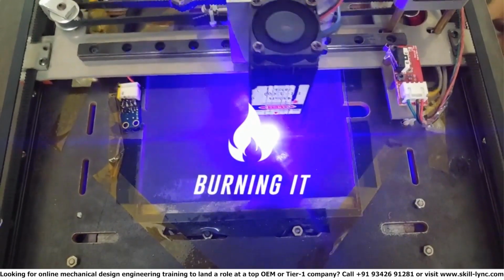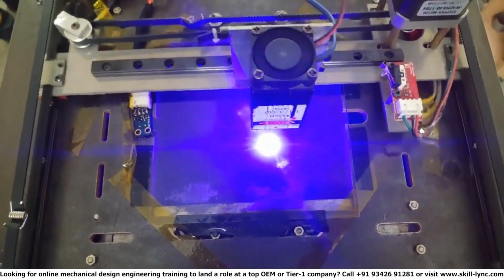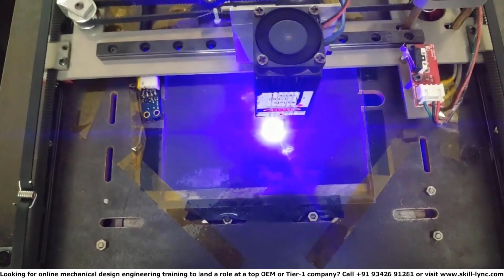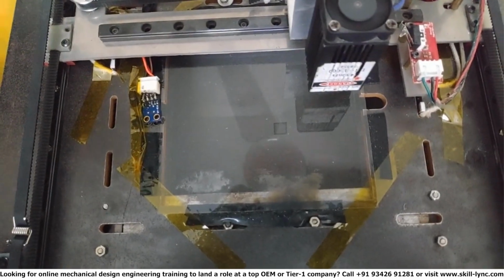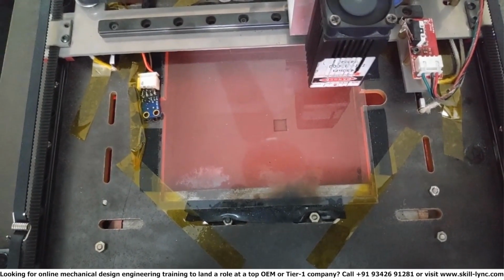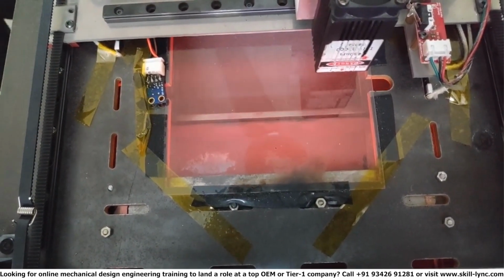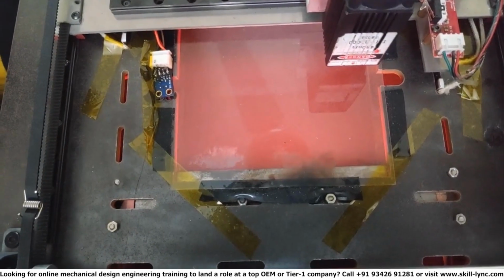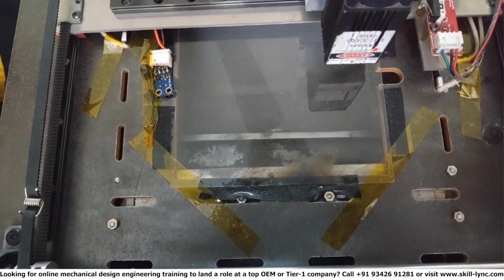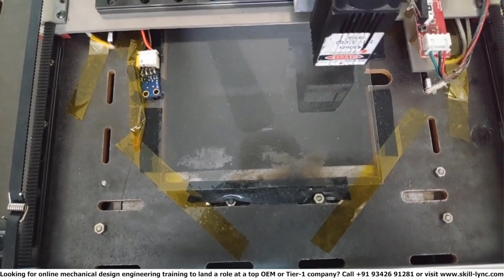All right, let's have a look at another one where you can see the equipment and the components a bit better. You can see the laser over here. There's a cooling fan attached to the laser to cool it down, because considering the amount of power output this laser has, it can easily overheat. You need a thermal sump over there to direct the heat produced in the component by the laser, because not all of the heat is directed down onto the build platform or workspace.